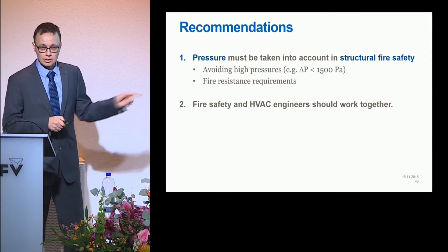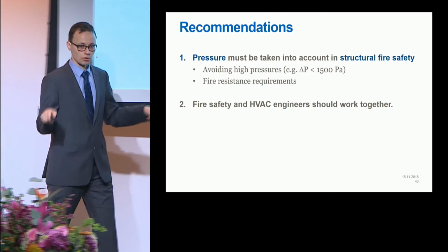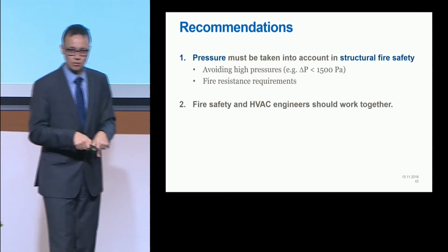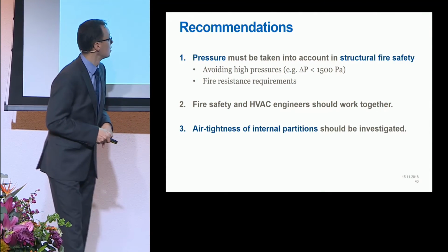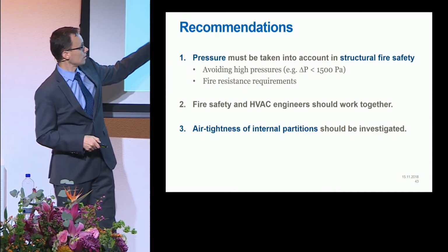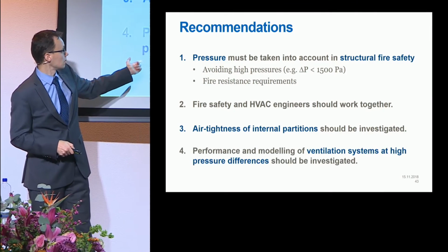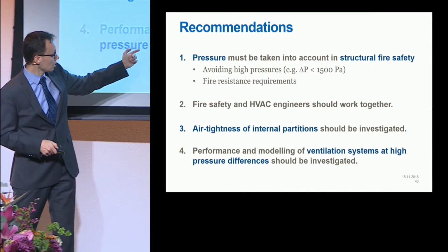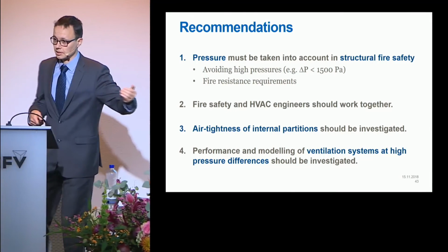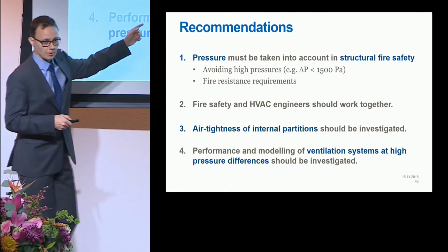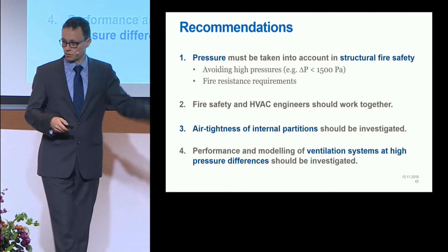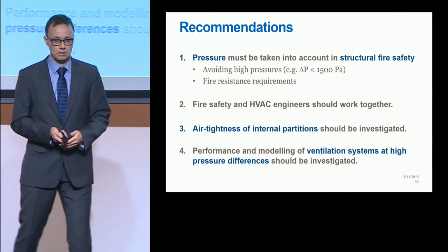What we learned is that fire engineers and HVAC engineers should actually work together if we want to use the ventilation system in order to manage the pressures. And also, we need more research on topics like airtightness of internal partitions and how the ventilation systems actually work at high pressure differences. HVAC engineers know how they design for normal conditions, but nobody really knows how they are going to work if we have 1,000 Pascal or 2,000 Pascal pressure differences.